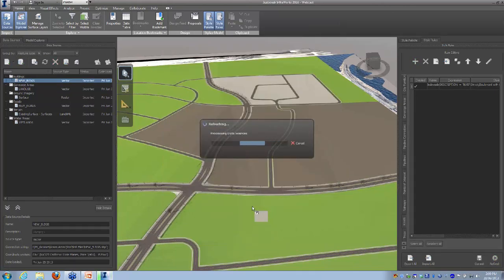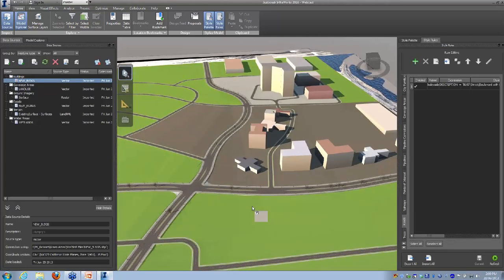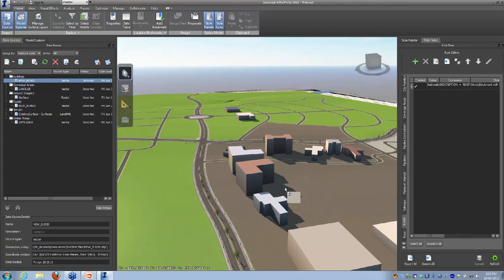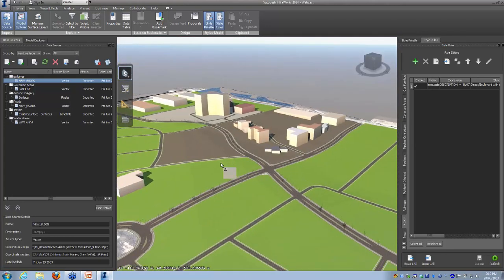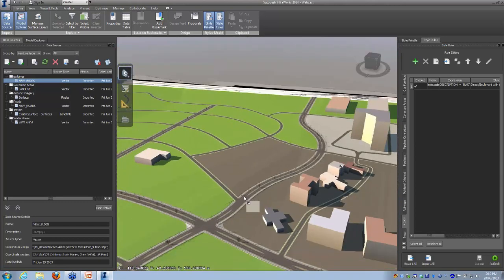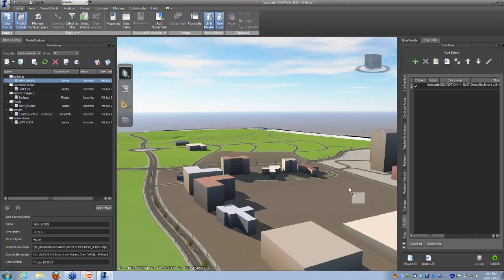So without going into any detail, just setting a roof height basically, we're getting a model that looks like that already. Okay. So it's just putting pastel shades on the roofs and the walls, so you get a general city layout. So this is all coming just from a shapefile. There's no 3D data there. This is generating its own 3D data based on the heights we told it for the roof height.